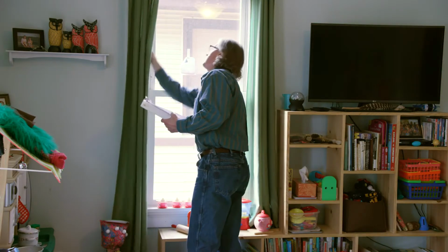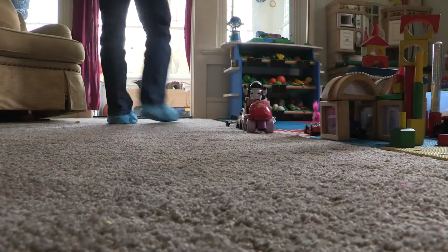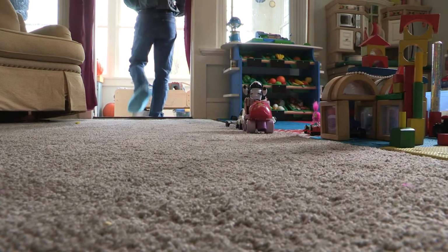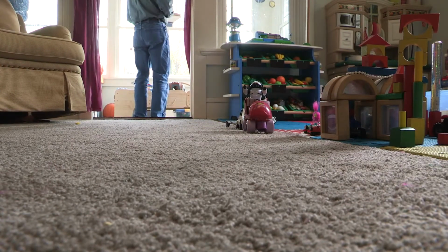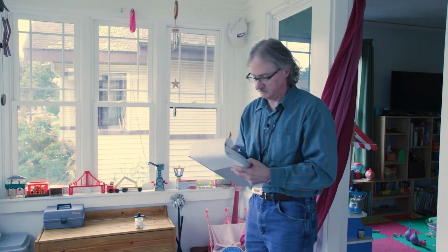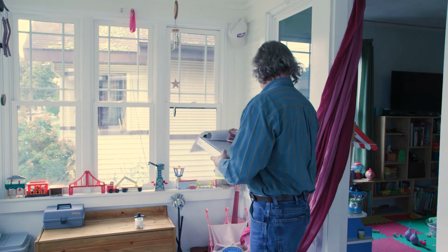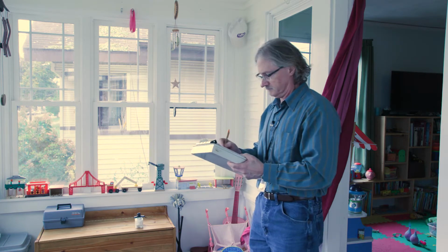It is not required, but a picture of the house also looks professional on the cover of your risk assessment report. Finish the building condition survey and visual assessment by going through the entire interior of the property. Document all signs of component or substrate failure. Document all locations that show evidence of surface coating deterioration, are friction or impact surfaces, or show chewing or bite marks. Make sure to include the basement and the attic if there is easy access to the space.